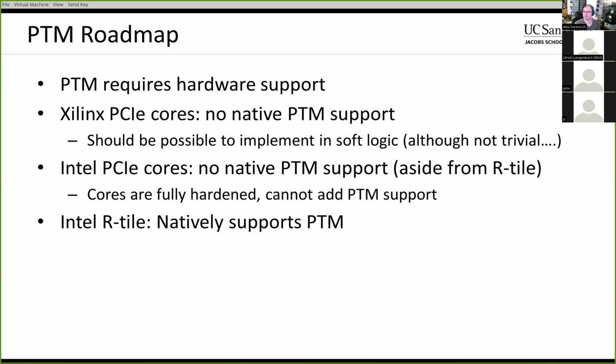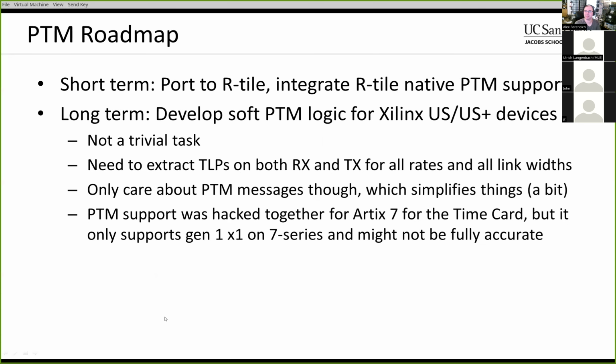So if we have an I-series dev kit, then we should be able to use PTM more or less out of the box. So that brings me to the actual plan here. Short term is to take Corundum, port it over to run on the R tile, and then integrate the R tile native PTM support just so we have an example of PTM running and we can make sure it works correctly and all that stuff.